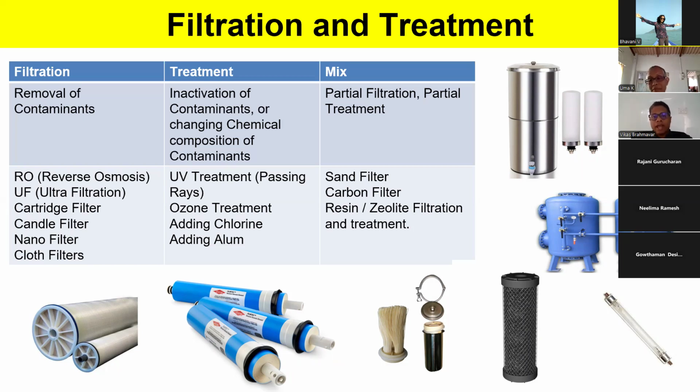So a carbon filter in any purifier, for Kaveri water, you need that basic carbon filter. If they have high chlorine in the municipal supply, let it pass through carbon, chlorine will go down, and then you take the water, so chlorine is gone. TOCs get reduced, smell gets reduced, color gets reduced.